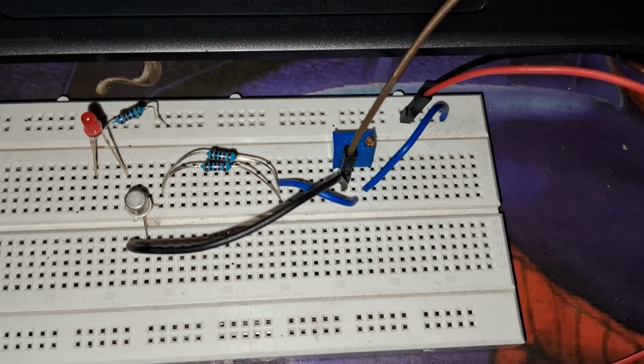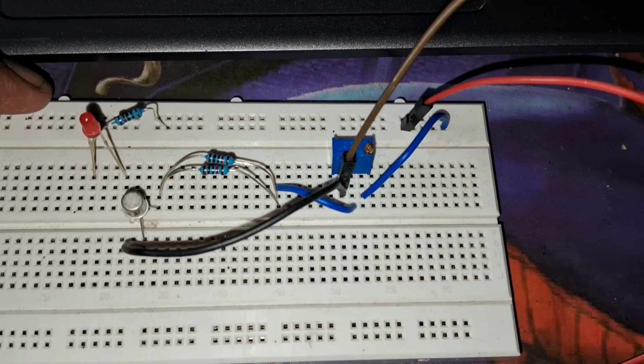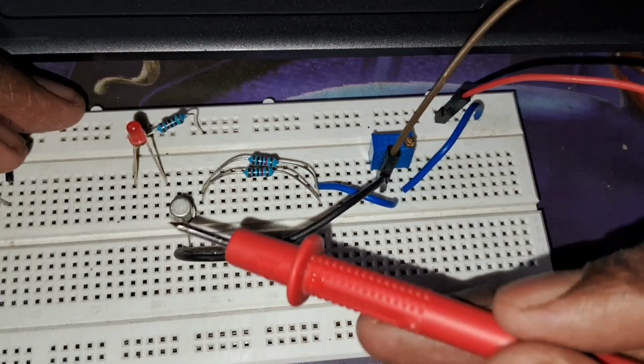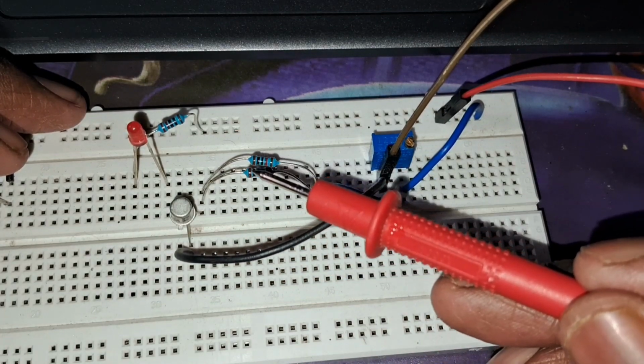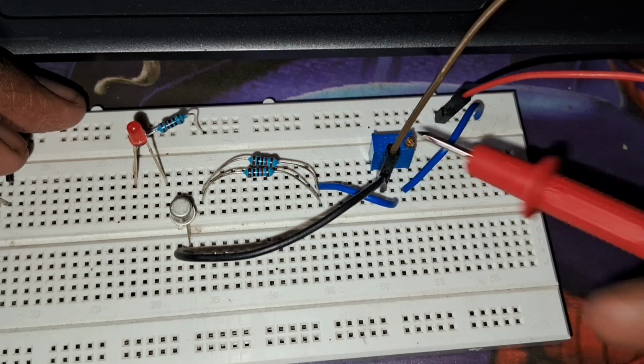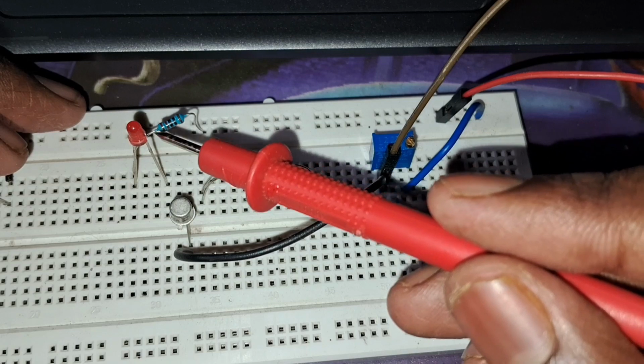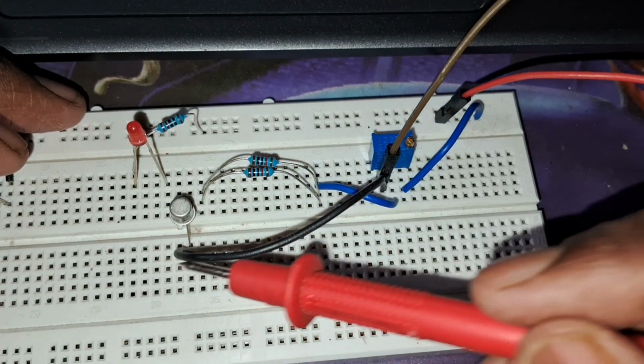Now I am moving towards part 2 of the experiment, driving an LED with the help of this BJT. I took a BJT and connected a 5K resistor, made from 10K and 10K in parallel, connected this to this potentiometer, and the collector is connected to this LED with a current limiting resistor, and the emitter point has been grounded.